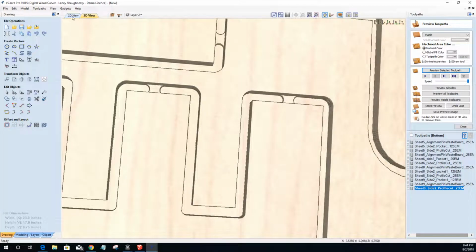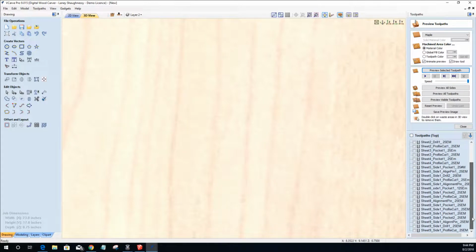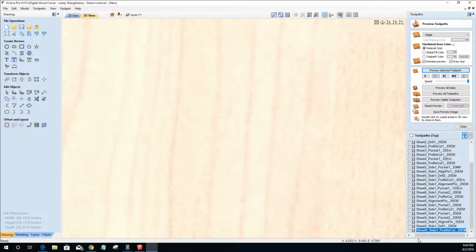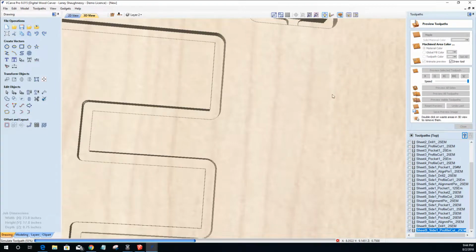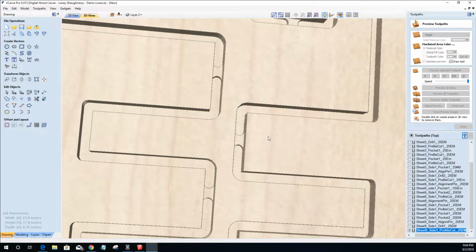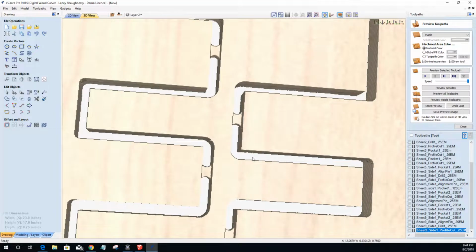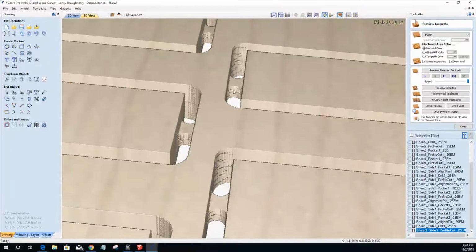Well, when I copy these vectors to the other side, the tabs are aligned in the exact same place as side 2. And so, therefore, when they cut, they're going to be 1/8 of an inch thick as well. And so now what we're left with, you can see there, is a 1/4 inch tab right there, from side 1 and side 2.